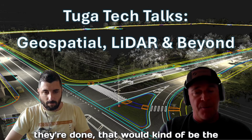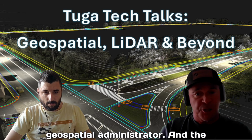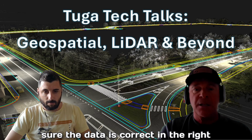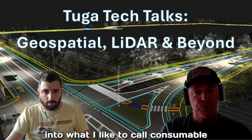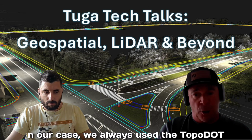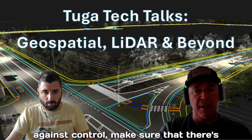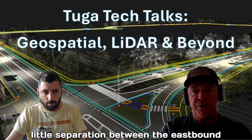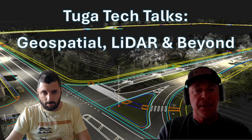Once they're done, that would be the end of their process. They would deliver it over to what I would call the geospatial administrator, who is responsible for double checking to make sure the data is correct and in the right place. Then they take those longer strips of data and tile them into what I like to call consumable pieces of data. In our case, we always used the Topodot tools to take the data, check it against control, make sure there are no anomalies, and look for separation. We want very little separation between the eastbound and westbound pass, and then we tile the data and get it ready.